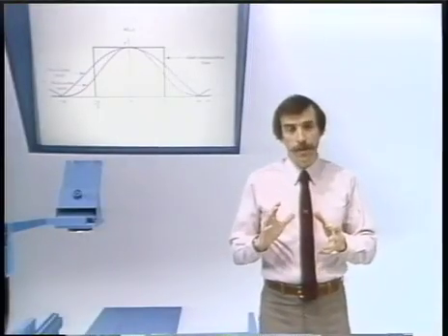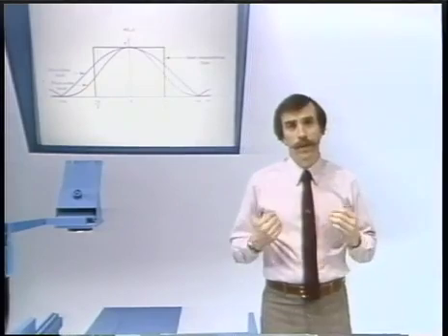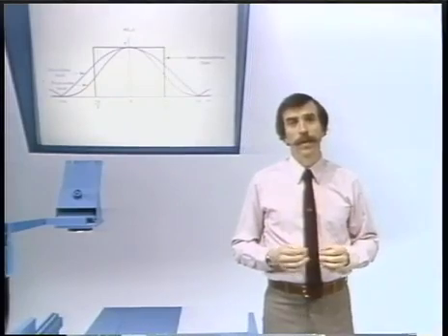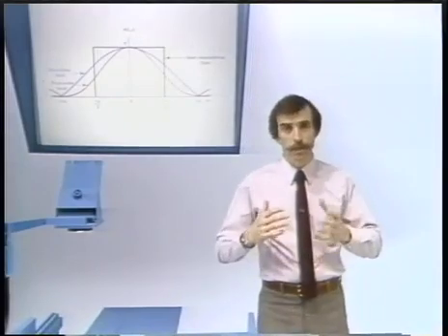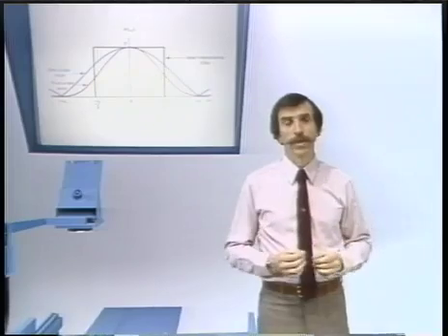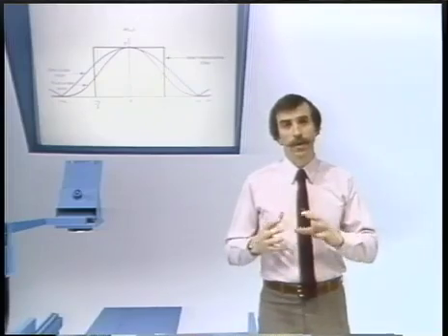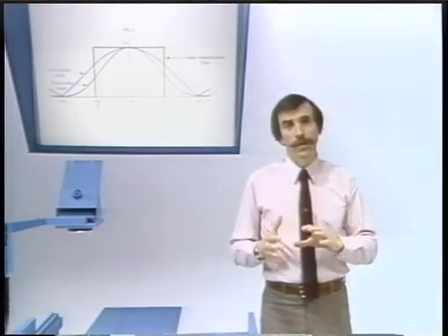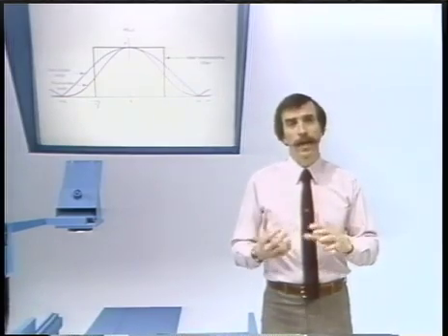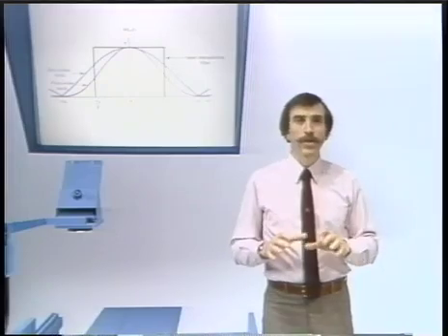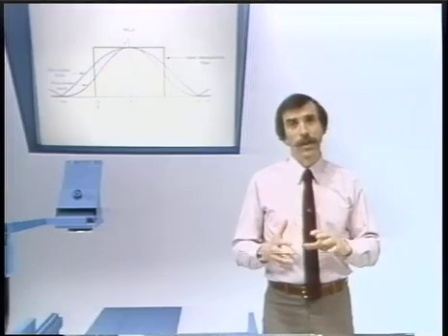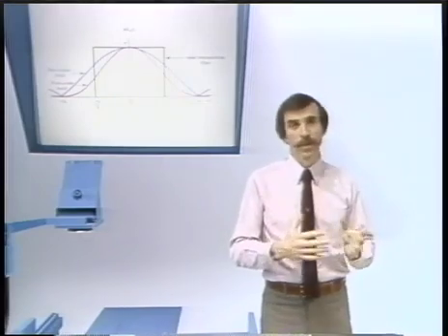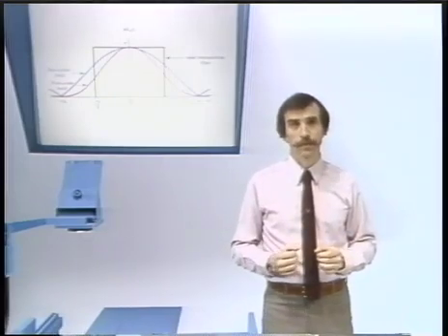Now, these images are, in fact, taken off a computer display, and a common procedure in computer-generated or displayed images is, in fact, the use of a zero-order hold. And if the sampling rate is high enough, then that actually works reasonably well. So now let's look at the result of applying a zero-order hold to the sampled image that I just showed.